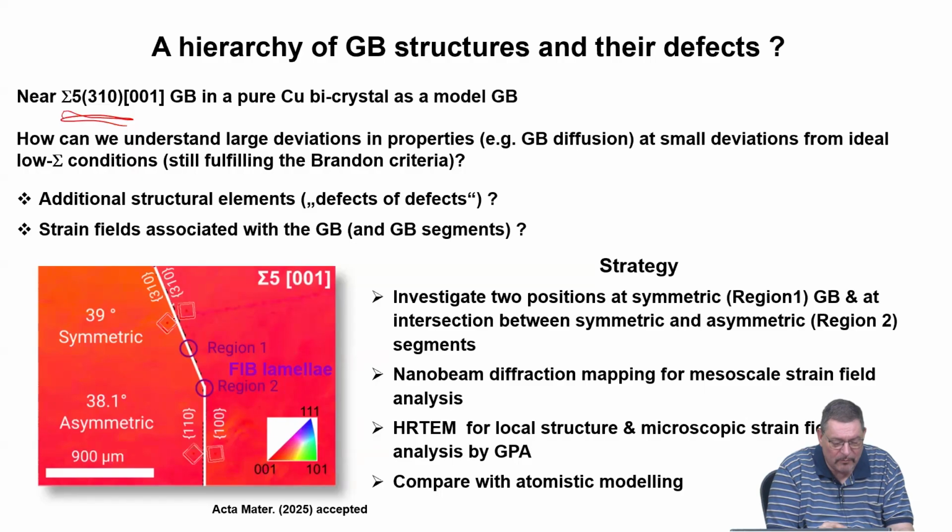And you see that in one grain boundary, you can have symmetric parts of the boundary, but you also have asymmetric regions. And by focused ion beam, sputtering with an ion beam in the SEM, you can select local regions and cut very small pieces of a material and then look specifically at different regions, so different types of boundaries from the same material.